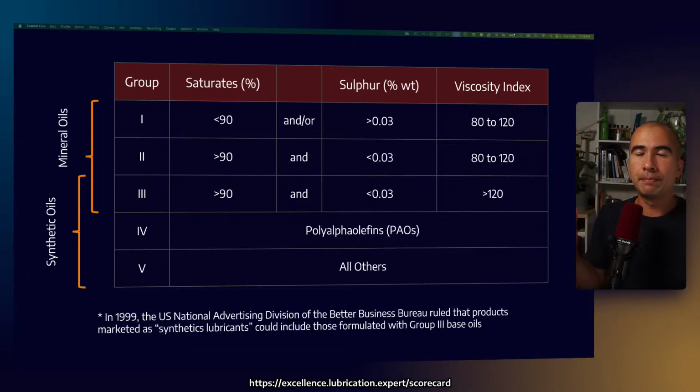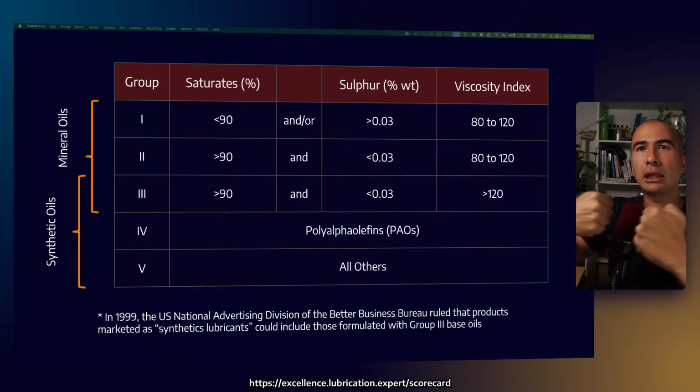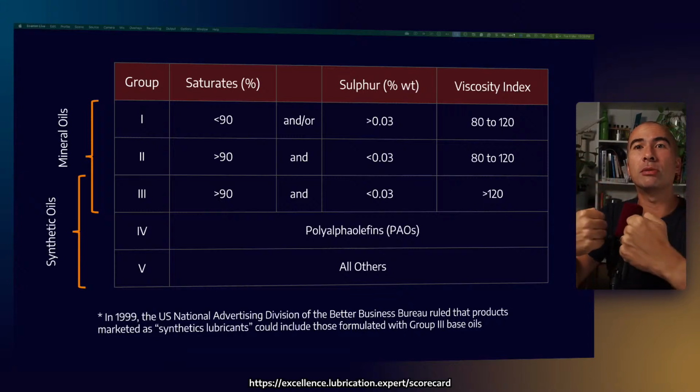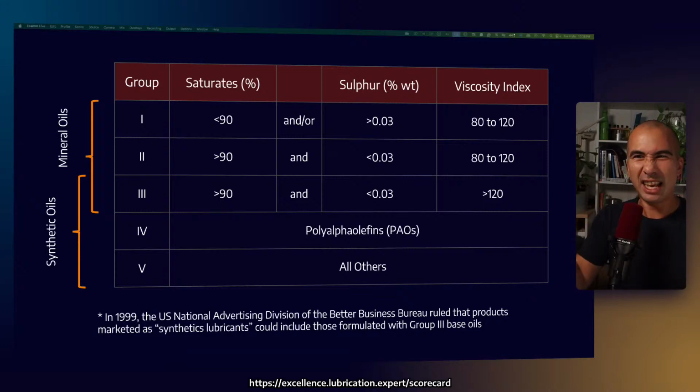What we want, if I could design the perfect molecule, is something that stays thick at hot temperatures. So think about an engine. What we want is something that is thin at cold temperatures so it can flow at startup. But once we start applying load to the engine and a lot of temperature, we want it to be thick. But Mother Nature gives us the exact opposite of what we want, and instead, most or all fluids thin out with temperature. So think about honey. It's really thick when you put it in the fridge. It's really thin when you heat it up on a stove.